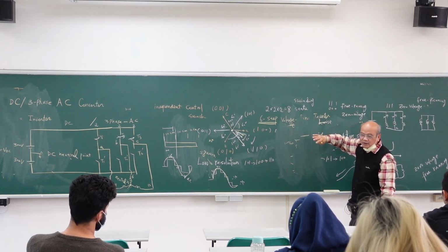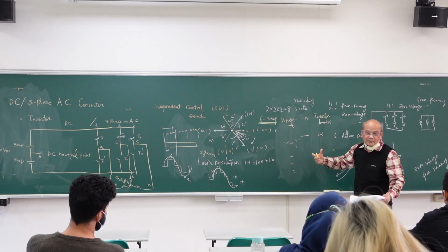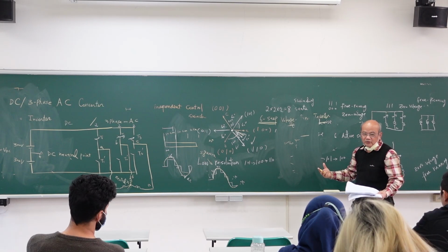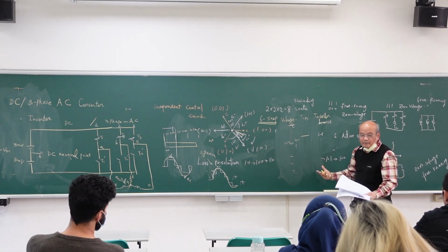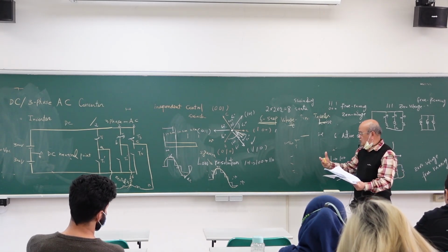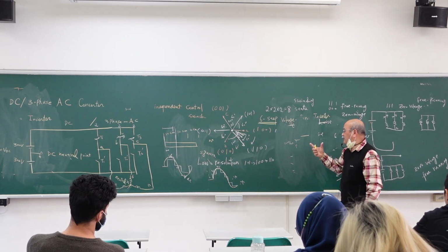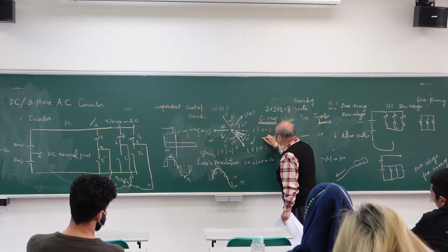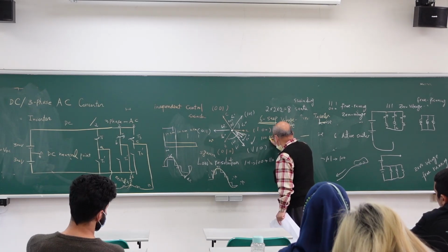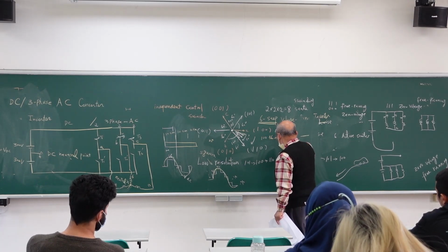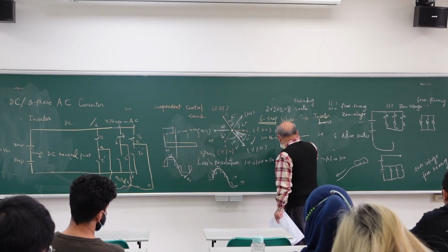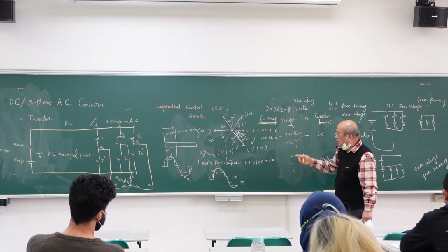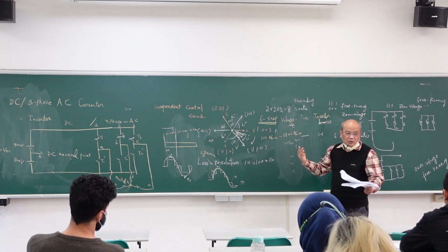Then it's shaking. Why? Because you do not get a sinusoidal waveform. You only provide a square waveform, so the harmonics are huge. If you put this kind of inverter into a motor, the speed you can adjust is from 100 RPM to 1,800 RPM. Below 100 RPM, it doesn't work.